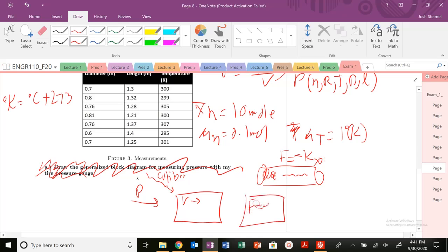But anyways, we're going to measure the displacement of that spring. So that volume is going to push on that piston. This pressure is going to be converted to force. That force is going to push and cause some displacement. So that's the transducing step. You could use this to look at the displacement, and your readout is manual, not digital. So it's just this stick that pops out, and then you measure with those tick marks.